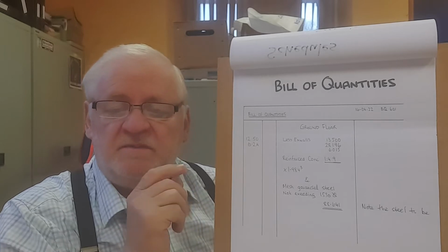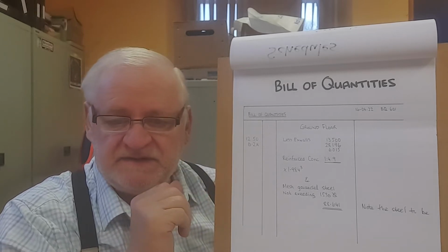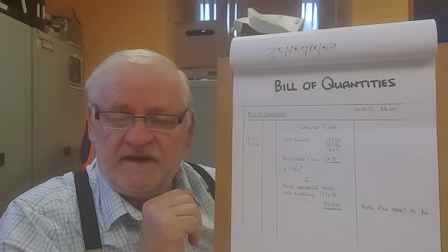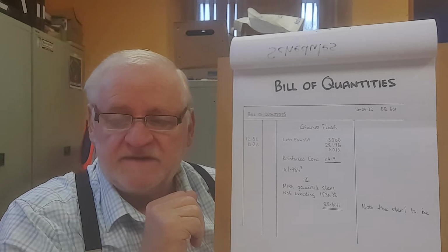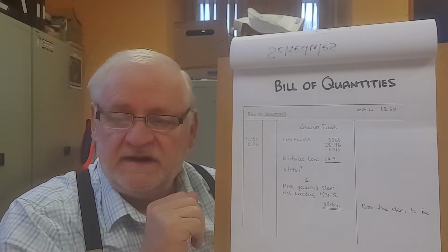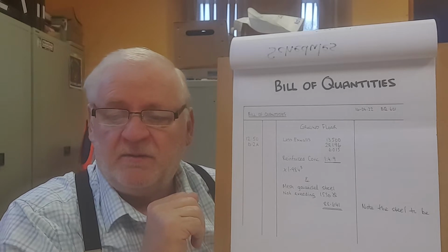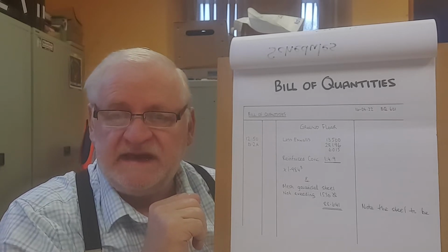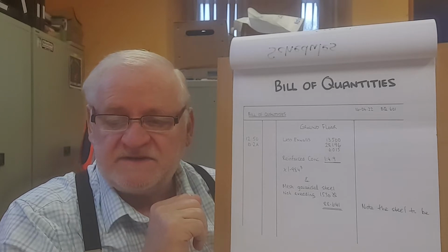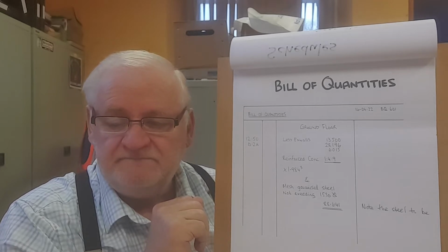Okay, so it would be an estimate. It's not a fixed sum, but it would be an estimate. Then there will finally be what's called the prime cost. Now, the prime cost covers all work undertaken by nominated subcontractors and by nominated suppliers and by statutory undertakings. And they are based on quotations for items of work which can be populated into the quote.